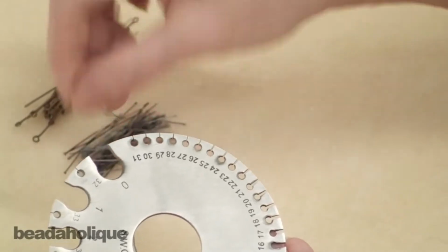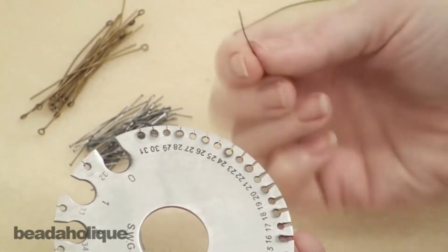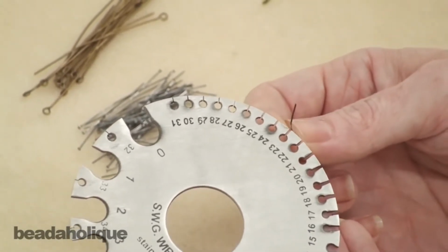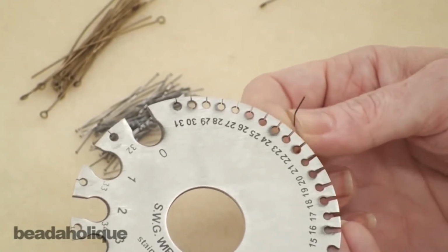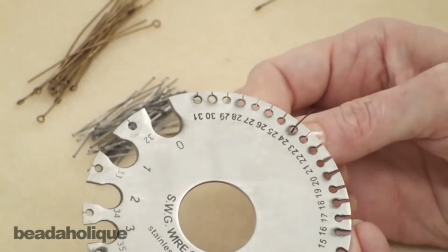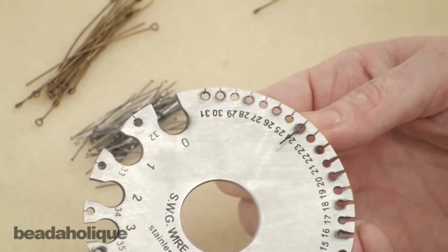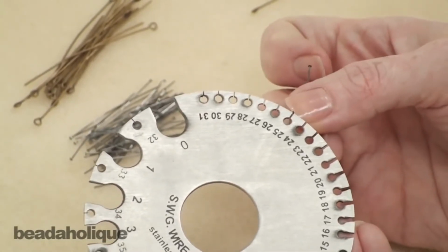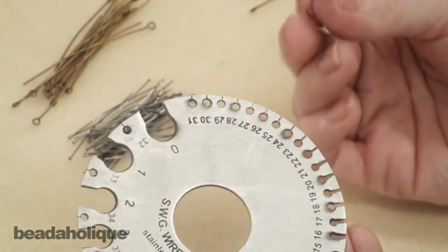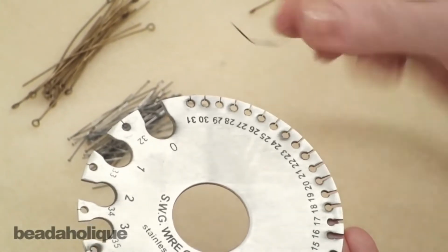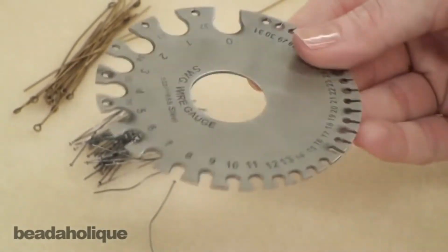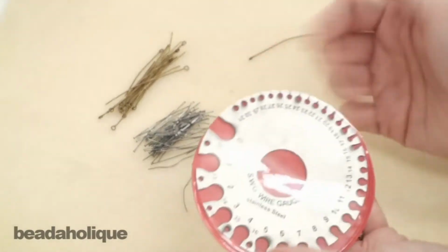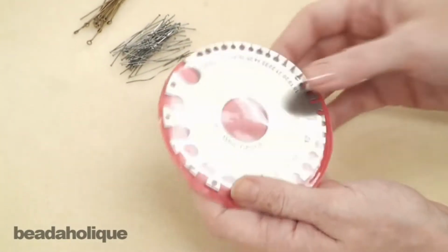I'm going to show you one more. I've got this little head pin here in gunmetal, and I can tell it's a bit thinner, so I'm going to try the 21. It goes right through really easily. 22, still going too easy. 23, pretty easy. 24, oops, I wiggled it and it went through, so that means it's going to fit. But I'm guessing it's 24 and it's not going to fit through a 25, but I'm just going to try it. Yep, it's not fitting. So this is going to be a 24 gauge gunmetal head pin. And that's all there is to using a wire gauge guide. It's a very handy tool. When you're not using it, make sure you put it back in its protective sleeve, and that's going to protect your fingers.